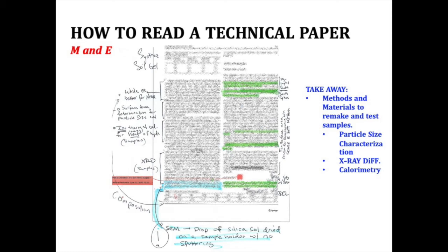The first peak is your calcium silicate hydrate development, then your second peak is your AFm development. So they give you one heck of an introduction into this. And not only that, but they go into what the expectations should be and why they think this change in the first peak is happening.